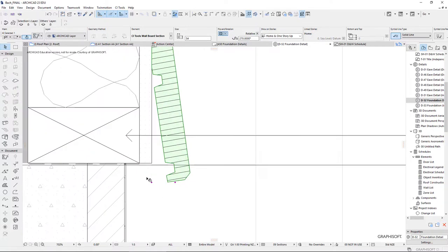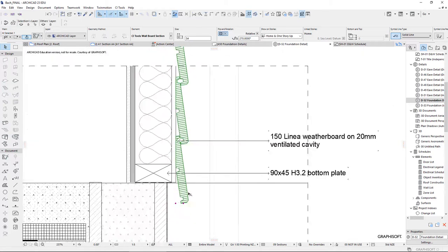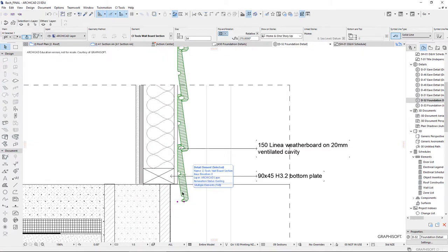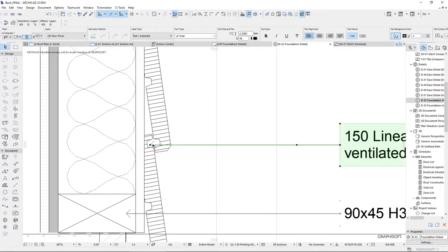Don't forget there has to be a distance between these, 50. So the easiest way to do it is if you start with it here, vertical, and then you go Control D, drag it down, and you can go 50, and there it is, it's 50 millimeters below. So let's pull that arrow back to there.